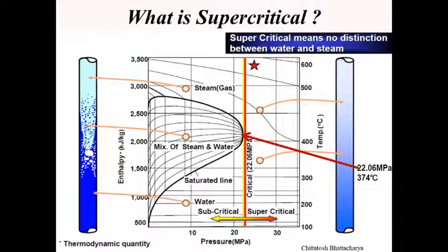This increased rate of heat transfer is actually dependent on circulation ratio, and the more we infuse heat within the steam and water mixture, there is more chance of increase in tube metal temperature. So we have to see that we can continue the addition of latent heat within the domain of nucleate boiling.